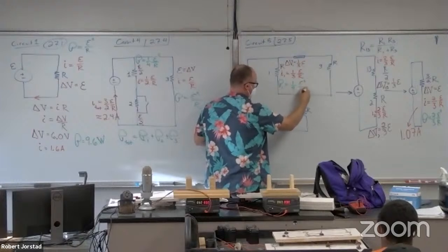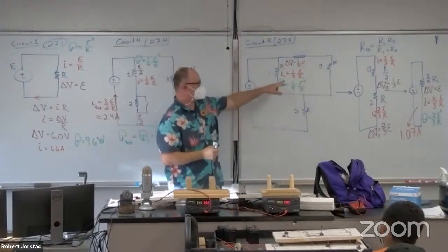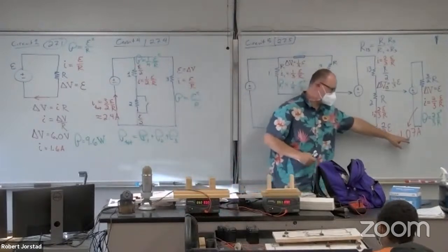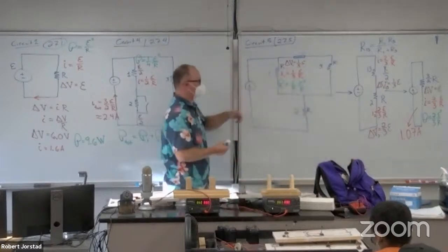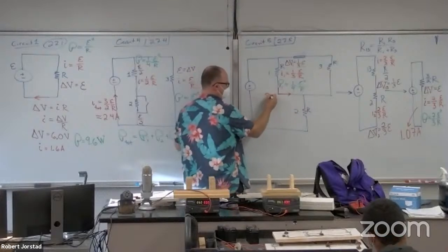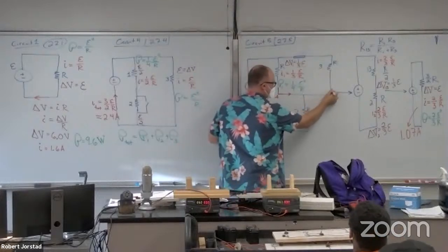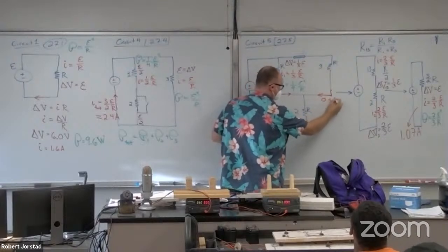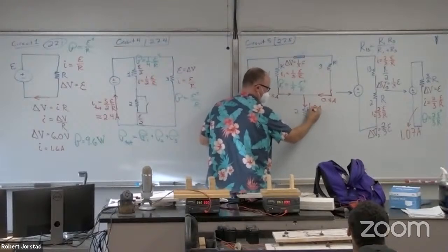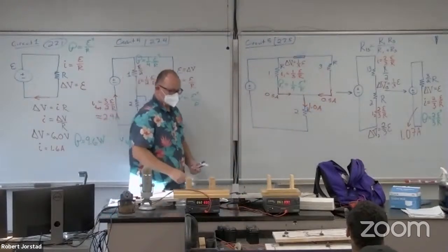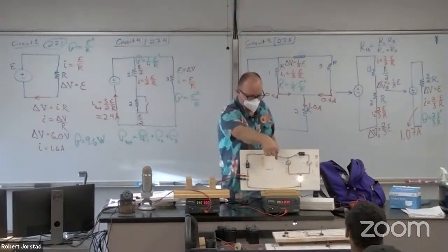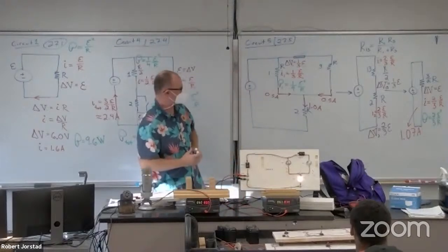This is why we don't see those bulbs lighting up. There's some current flowing through them. In particular, we know if the total is about this, we're expecting about a 1/2 amp through each of these. So in this case, I'm just going to round this. This is about 0.5 amps. This is about 0.5 amps. And then we expect them to combine and push out at least about an amp, right? Again, it's not exactly true, is it? What's the number of amps we get for the total?